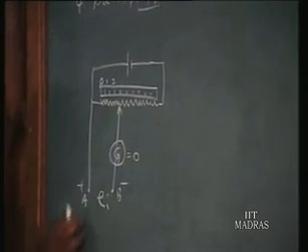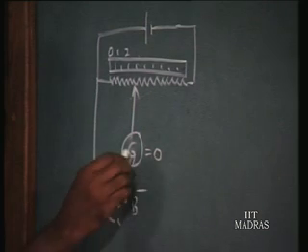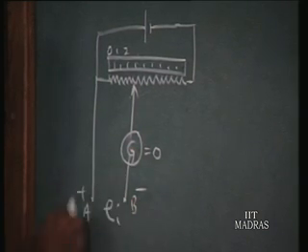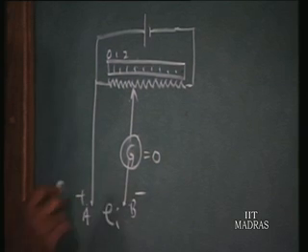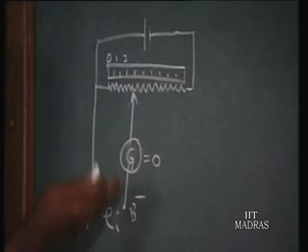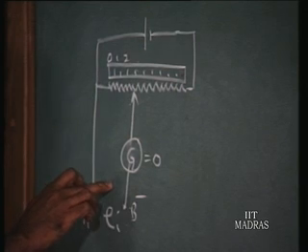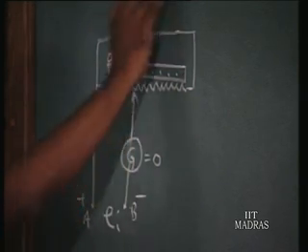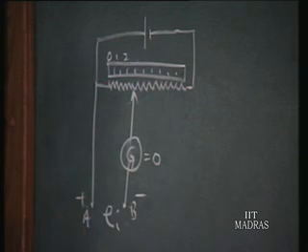This is the input medium. We draw 0 current. The galvanometer is an ammeter. When the reading is 0, it means absolutely no current is drawn from here, and in that situation we are measuring the voltage. So it is equivalent to the input impedance for this measurement being infinity. This is null balance, where we make the reading 0 by adjusting this contact. So you will find the loading effect is 0.